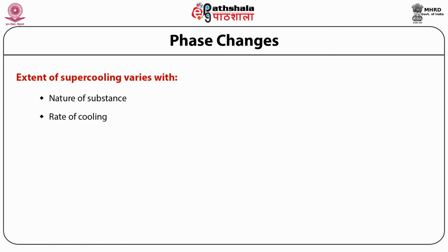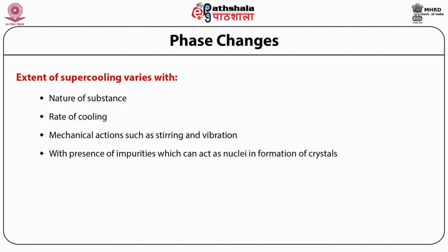The extent of supercooling also depends on mechanical actions such as stirring and vibrations, and with the presence of impurities which can act as nuclei in the formation of the crystals.